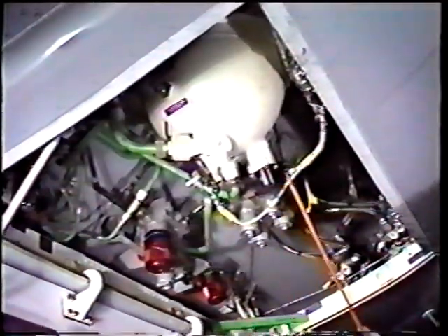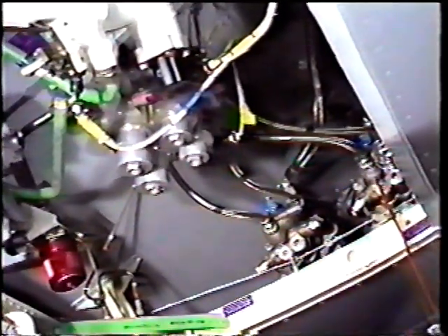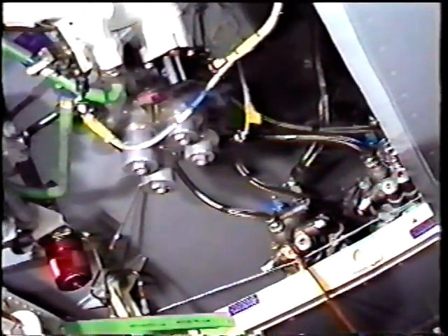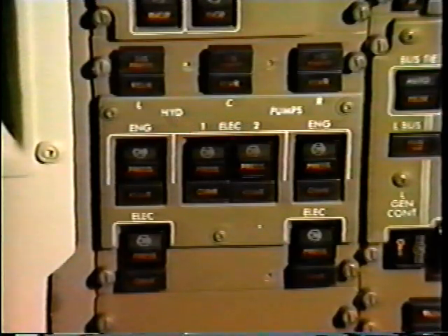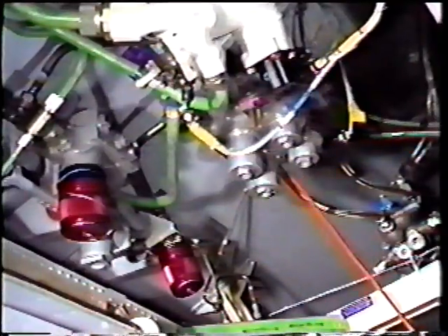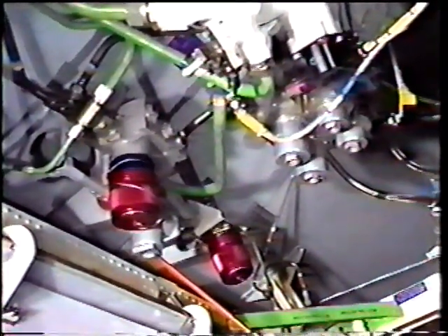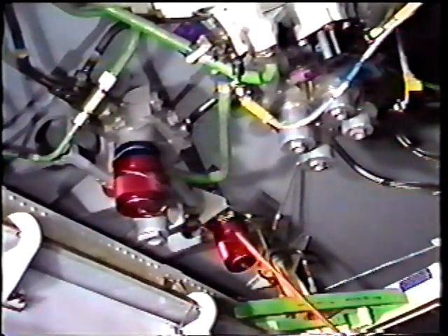Components for the center system are located on the left aft body fairing. Access is provided by opening an access panel. The center system hydraulic reservoir is here. On the reservoir are a quantity transmitter and a temperature transmitter. Located to the rear of the compartment are two ACMPs. Two pump switches located on the P5 overhead panel supply electric power to the ACMPs. Forward of the pumps are a dual pressure case drain filter module, the return filter module, the pressure ground connection, and the return ground connection.